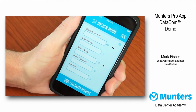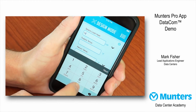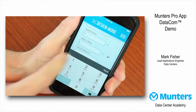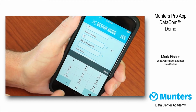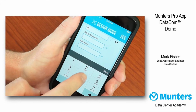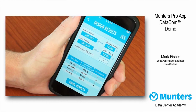So there's several inputs on this screen, and I am going to simulate a hypothetical data center that is 1200 kilowatts, and we're going to be running a supply temperature of 72 degrees Fahrenheit. And I want to run a 20-degree delta T, so I can either plug in 92 for my return temp, or you can actually toggle between delta T if it's easier to put it in that way. I'm going to set the room dew point at 54, and I'm going to run it at sea level. Those are all the inputs I need, and now I'll be able to see the results by hitting the calculate